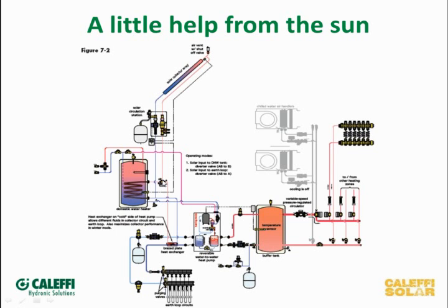Again, you can see a three-way diverting valve there, so we've got the ability now for the solar to come on in the morning and cover your domestic hot water load first in that solar tank, in the SolarCon tank, and then it can toggle over, and in this case, we're putting it into the loop field. So if you've got a job where you want to start maybe in the fall months, you want to start charging up your loop field, put some temperature down into the ground there to help with your heat pump when the heating season rolls around. That's what we're doing with any excess heat from the solar. We can put it into the loop field.